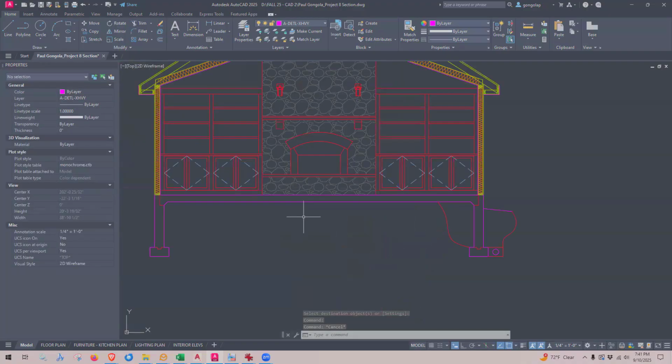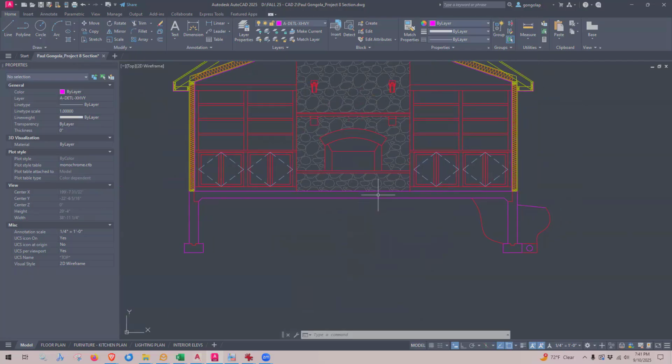All right, so the last thing I want to do, I think, before we call it quits tonight, is do my stone. The floor slab is sitting on top of some crushed stone, and that was, I believe, a 4-inch bed of stone. So I'm going to offset the bottom of my floor slab 4 inches. Wait, was it 4 or 6? Let me make sure. 4-inch gravel.